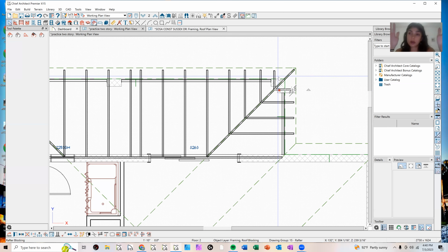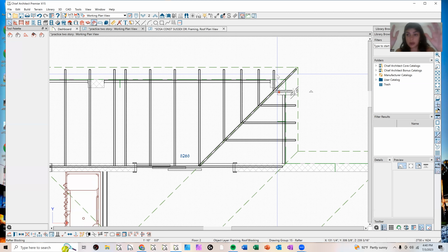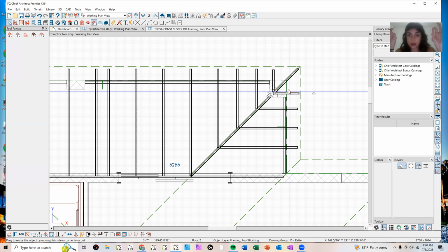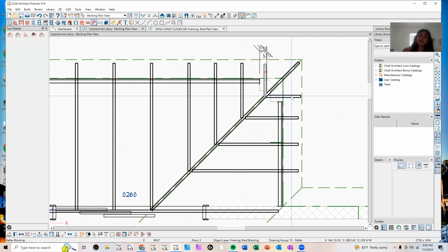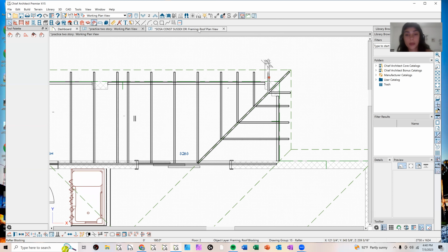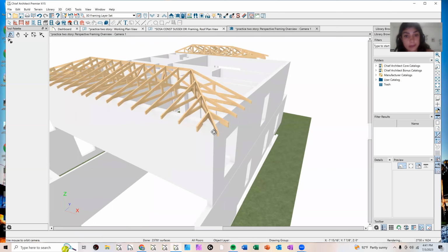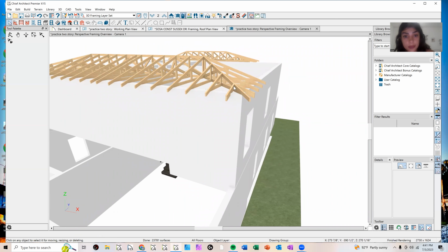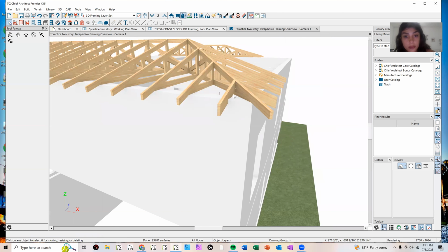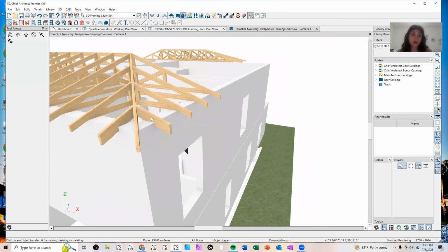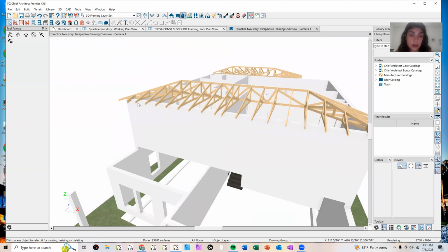Blocking should be every corner or start to end of the roof. It's gonna be on the end right here on the corner where this truss won't fit anymore. So if we look, you look in here, this won't fit anymore. So they have to just put one piece of wood instead of a truss. So that's what the blocking is. If it's an end piece that's a gable, then you wouldn't have to have blocking.